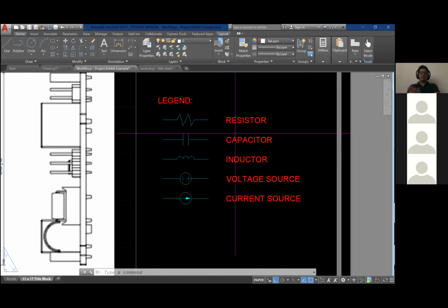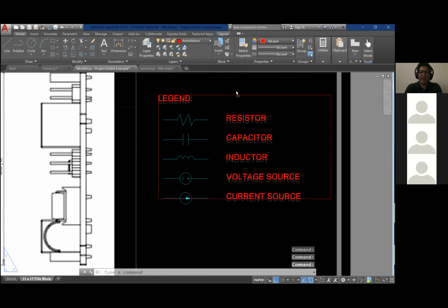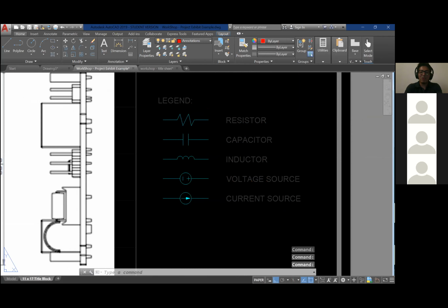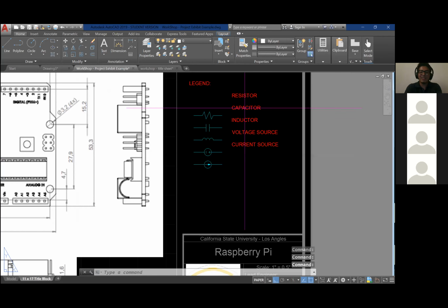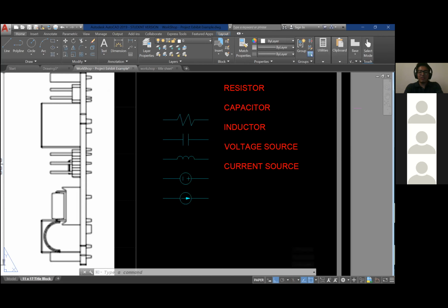I don't know if you guys know what topographical maps are, but they have those in the background. And AutoCAD has this feature, I'll show you right now, where if you select something and then click on it again and drag it, it'll move it without you having to type in the move command. You see how it just moved it? So I'm going to click undo. You can also just type in undo.